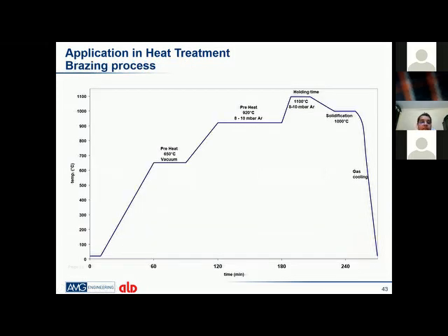Similarly, in the brazing application, when vacuum brazing has been done, you will see the quality of the part is very different from what we see in the conventional process. Because of the capillary reaction of the brazing paste, everything is very intact, and there is no post process, because the post process has been removed and we get a good part.